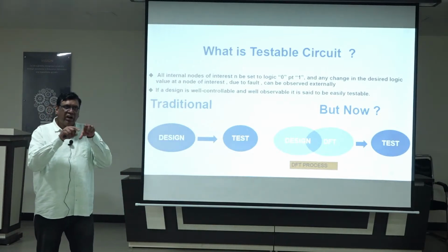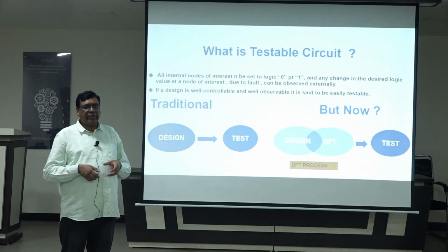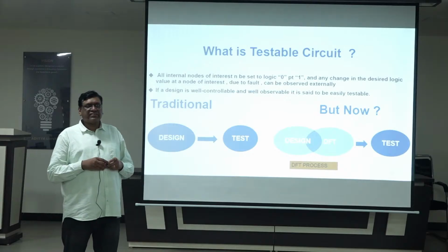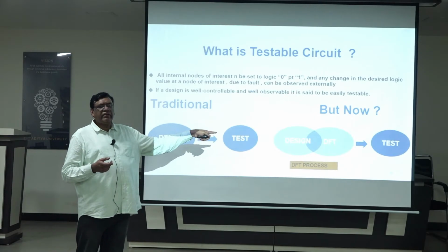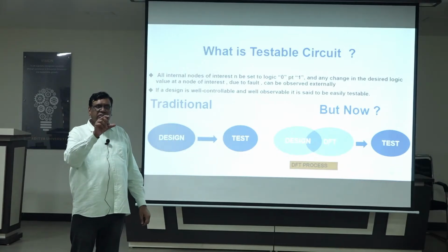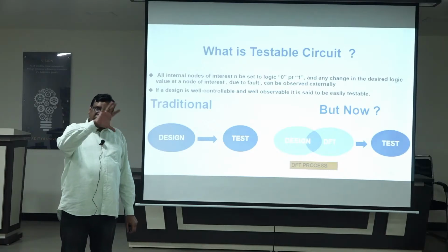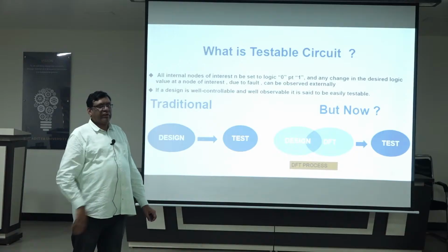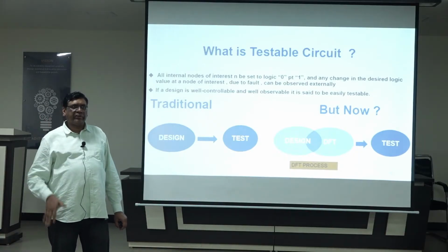This DFT logic we can't read after packaging has happened. Before packaging only we can read it. Flexibility of that will be grounded for security reasons. What people are doing is that with this DFT they are hacking. They are hacking the chips using the DFT resources. They are trying to understand and replicate the internal content of the chip using DFT hardware. So they will bury it inside once the chip is manufactured.